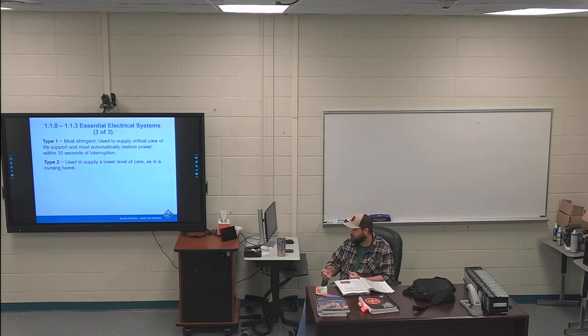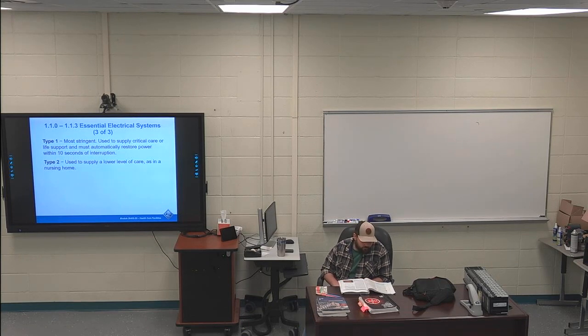So a throwover switch is just a switch used to give temporary power to get people out, make stuff happen. But as soon as you're done, you open that switch back up and you're using that power for more emergency systems. 113, other healthcare facilities.